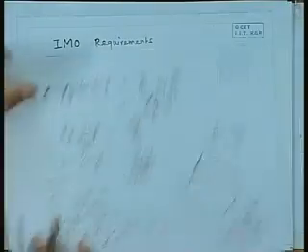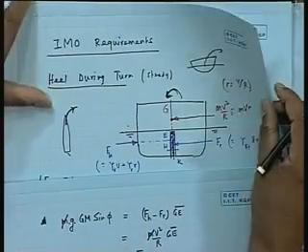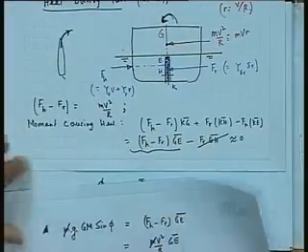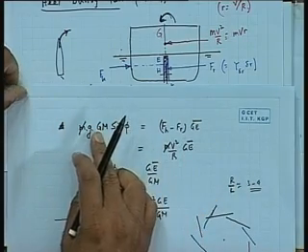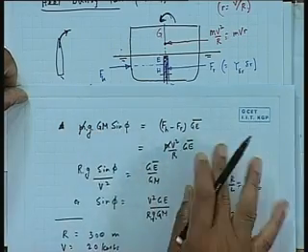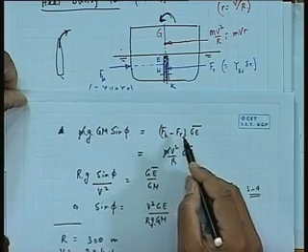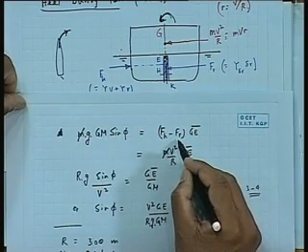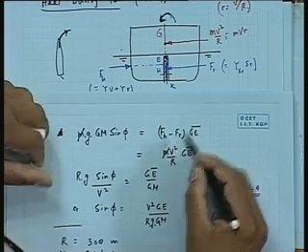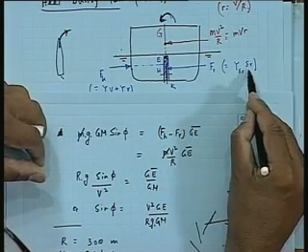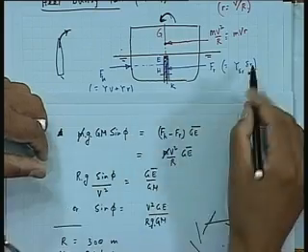If you look at that, I will just put it in this way, then it will be easier. See here, I have got Fh minus Fr into G in this formula. Now suddenly I want to reduce Fr. If I make Fr 0, because suddenly I turn my rudder angle to 0, Fr is after all Y delta times delta. So suddenly I make delta 0.